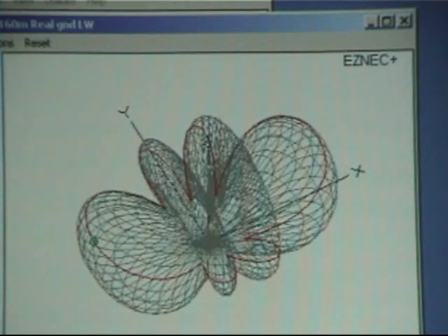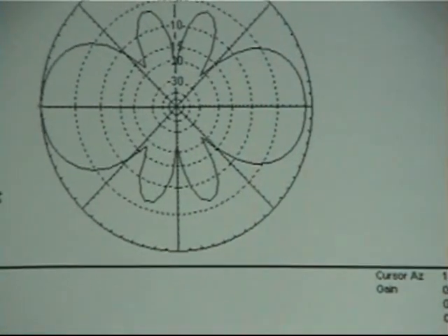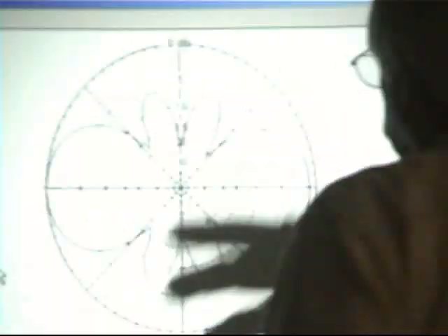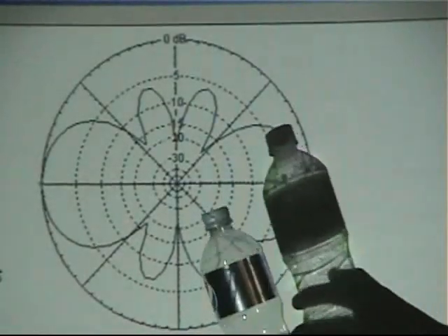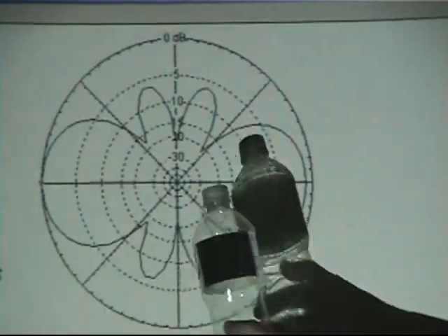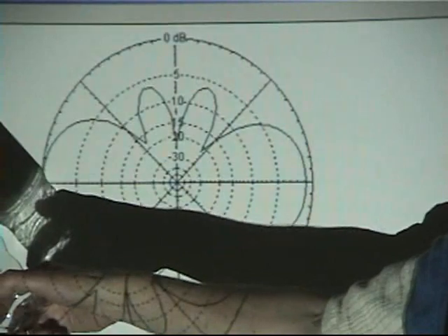And if I do an azimuth slice, now, at ground level, at zero up from the horizon, I don't get anything in this case because I got earth there. So this cut is going to be up at 35 degrees, and we'll do an elevation cut in a sec. This just shows the azimuth pattern, and I got lobes. So cool for me, because in this contest, there's a lot of folks on the East Coast, and there's some out in the West Coast.